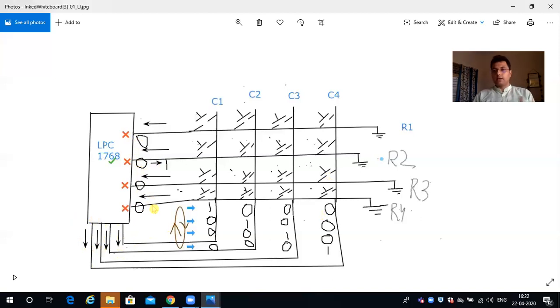So as and when any value becomes 1, it triggers that something is being pressed. Then over that row, 4 column options are available, and out of those 4 column options, we have to zero in on one specific column and exclusively figure out which column switch was pressed.